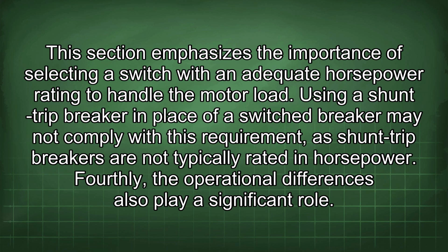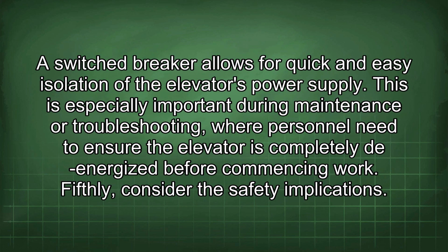Fourthly, the operational differences also play a significant role. A switch breaker allows for quick and easy isolation of the elevator's power supply. This is especially important during maintenance or troubleshooting, where personnel need to ensure the elevator is completely de-energized before commencing work. Fifthly, consider the safety implications.